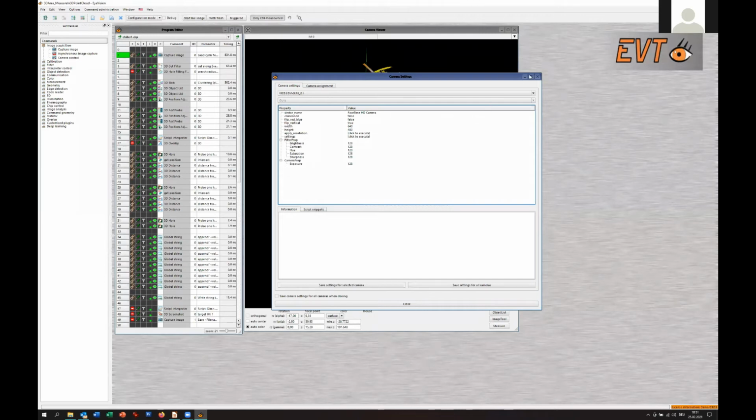If you have a 3D camera, of course, you see all the 3D settings, like, for example, if it's a laser camera, a triangulation-based camera, setting up the laser system, and also the things you see here, like brightness, contrast, and so on. If you have a GigE-based camera, you see the complete GigE Vision tree with all the settings the manufacturer gives you to control the camera. Most of the 3D sensors are GenICam based, so you have a full GenICam tree and full access to everything.